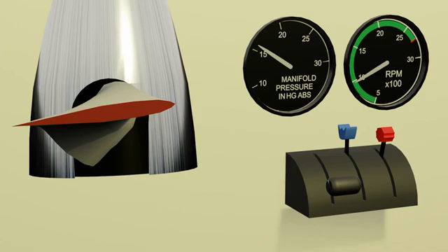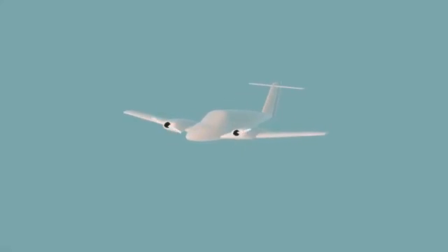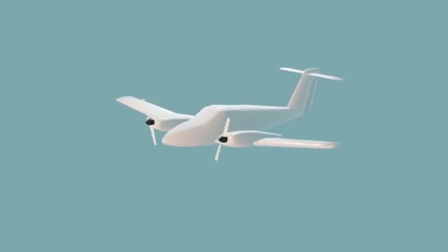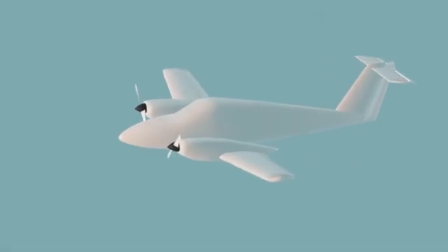During shutdown, the blades are kept at fine pitch too. Fine pitch means less opposing torque, which will make the starter motor's job easier next time we start up. To summarize, the propeller lever can be thought of as the gear selector on your bicycle or car. Low gear or fine pitch is for low speeds at takeoff and approach, and high gear or coarse pitch is for cruising at altitude. The constant speed propeller is a complex and powerful tool that pilots like you can use to maximize the engine's capabilities across all phases of flight.